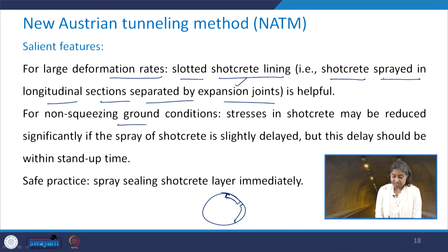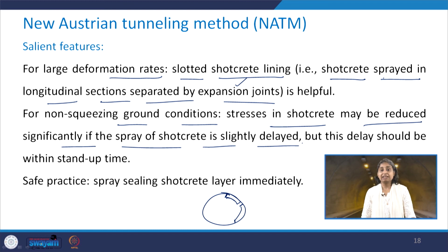For non-squeezing ground conditions, stresses in the shotcrete may be reduced significantly if the spray of the shotcrete is slightly delayed, but this delay should be within stand-up time. What happens when we delay the installation of the support or the spray of the concrete in this case?